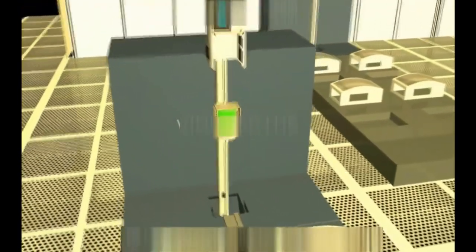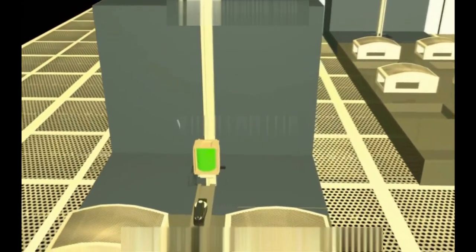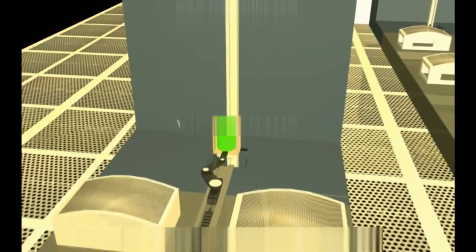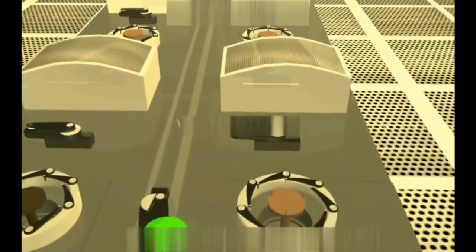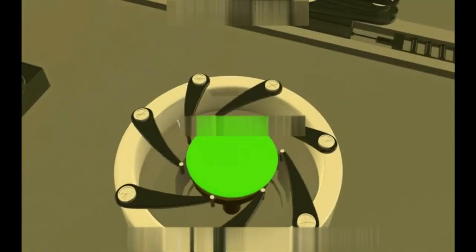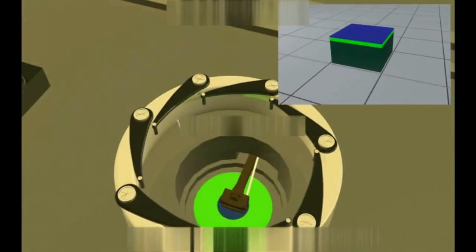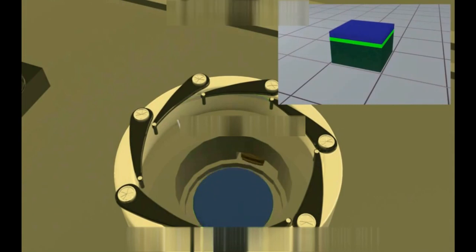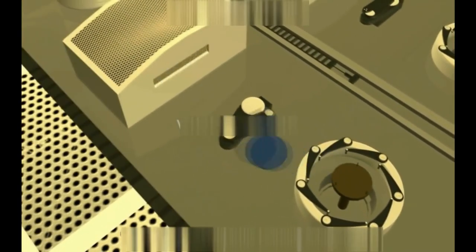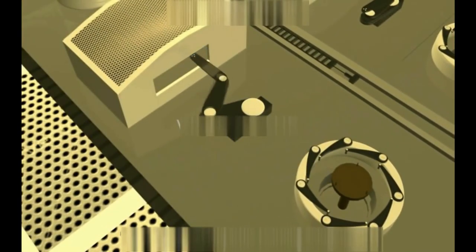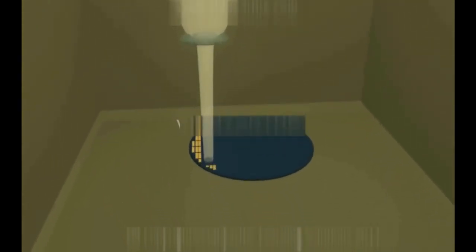The third and final step in the fabrication process is called lithography and is the most important step in the fabrication process. This process involves a series of fully automated steps where wafers are first deposited with a light-sensitive photoresist material. These wafers are then exposed to specific light patterns which are defined by the GDS format, which is the result of the integrated circuit's back-end development flow.